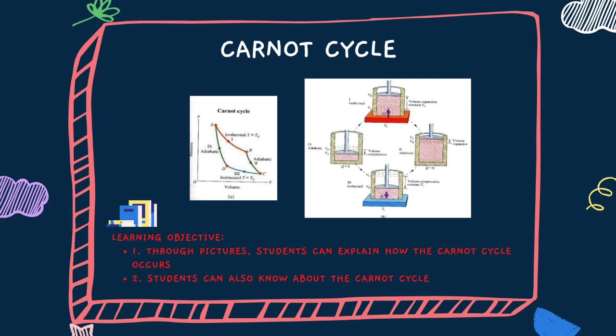And then picture B is the work cycle of the Carnot engine. It has 4 stages. Stage 1 is an isothermal expansion, and this expansion takes place with the cylinder in contact with the heat source, of red color, at high temperature TH. Stage 2 is an adiabatic stage in which the volume increases slowly while the temperature and pressure decrease. Stage 3 corresponds to the isothermal compression of the gas at the low temperature TC, and in stage 4 the adiabatic compression of the gas occurs, which increases the temperature and pressure until they return to the initial condition in A.